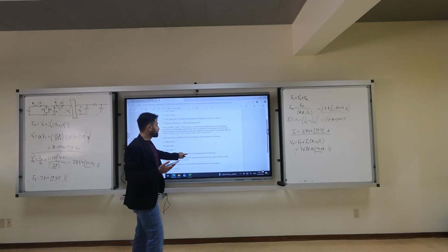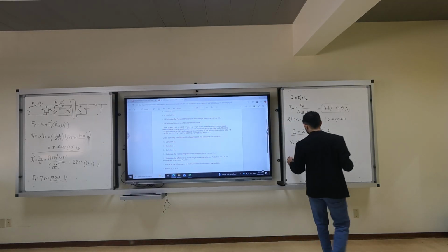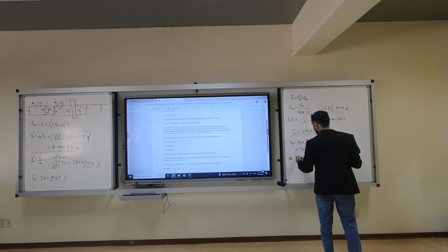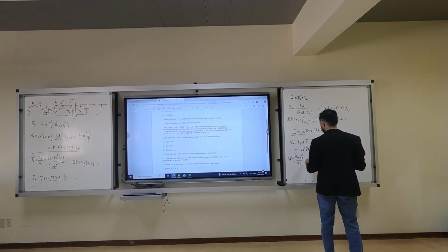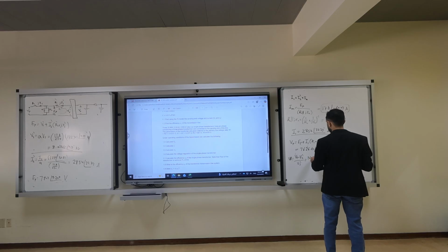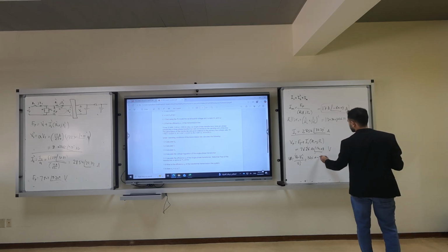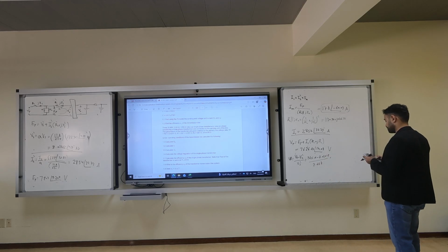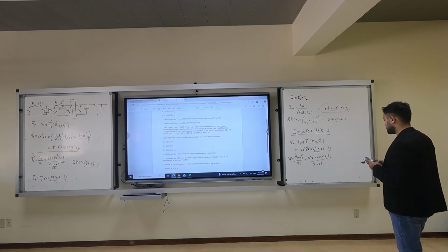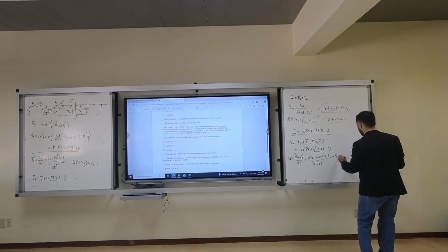So, what is the voltage regulation of the transformer? What is the voltage regulation of the transformer? VP minus Vs prime over Vs prime, right? Take the magnitude 7626 minus 8037 divided by 8037. This is key. 7626 minus 8037, which is maybe minus 5.11%.